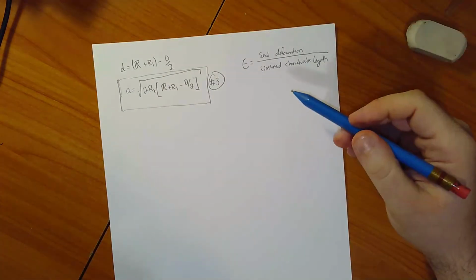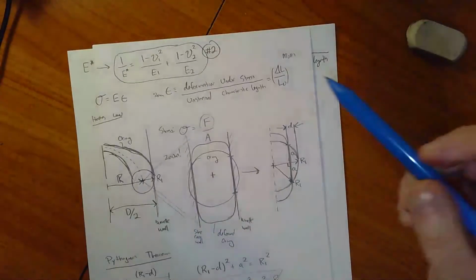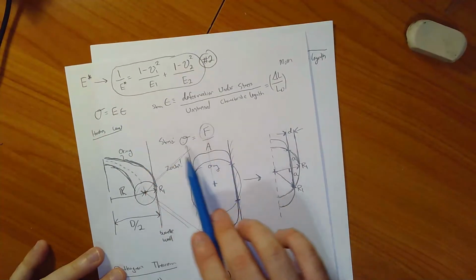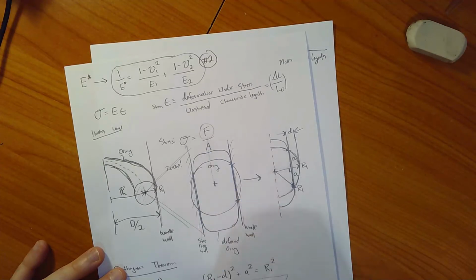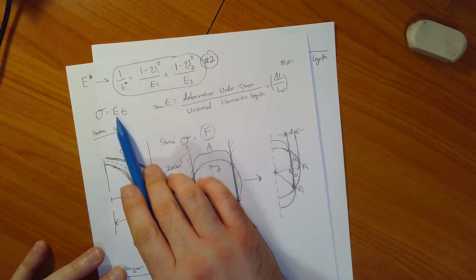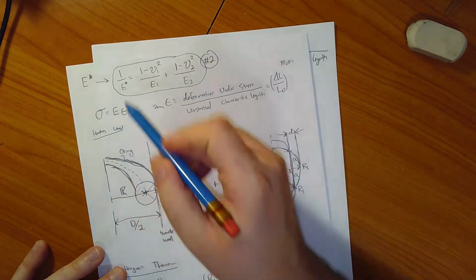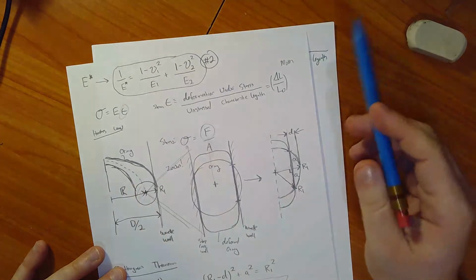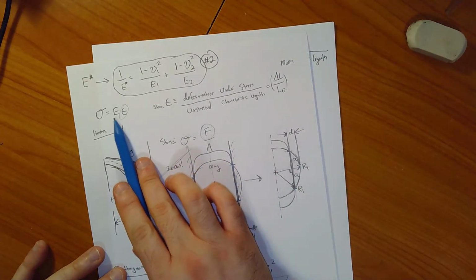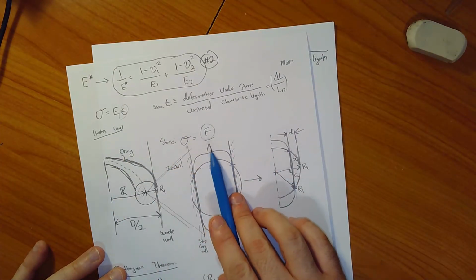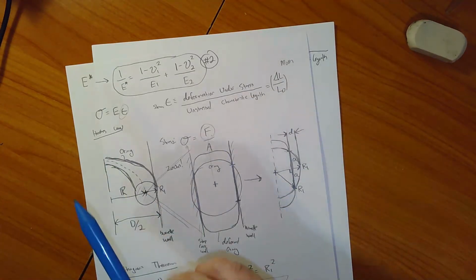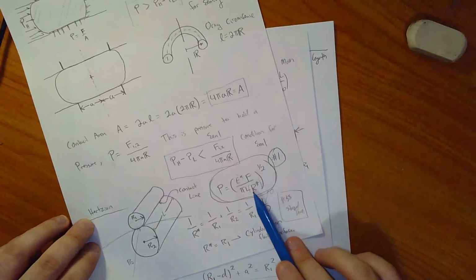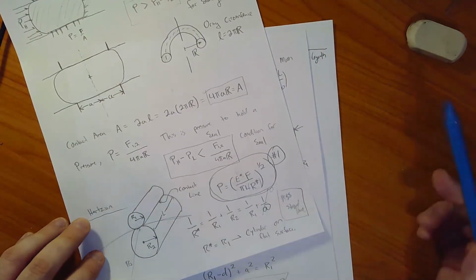Of course, the reason that I need the strain is because I'm trying to use Hooke's law, and I now have an expression for this area, because I know A. I know the Young's modulus. I can look that up for my rubber O-ring. So that's the strain, and if I know the strain, Young's modulus and A, I can put all those pieces together and get an expression for F that I can then stick into my Hertzian expression here. I know everything else, and I can solve for that pressure.